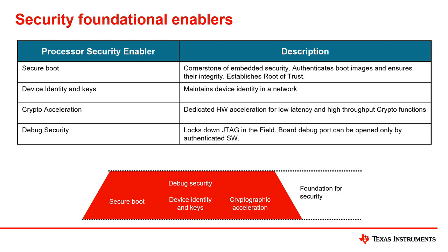Crypto acceleration is really one of the hallmarks of enabling security. It's going to be used not only in Secure Boot, but in encrypting data as it's sent around the system. And accelerators are necessary for this, particularly in the early boot phases when high-powered processors aren't available to do the cryptographic operations. So acceleration is going to help some of the rest of the boot process, as well as just make it easier for the system. And it guarantees more security, since these hardware implemented accelerators are inherently more secure than a software accelerator, for example.